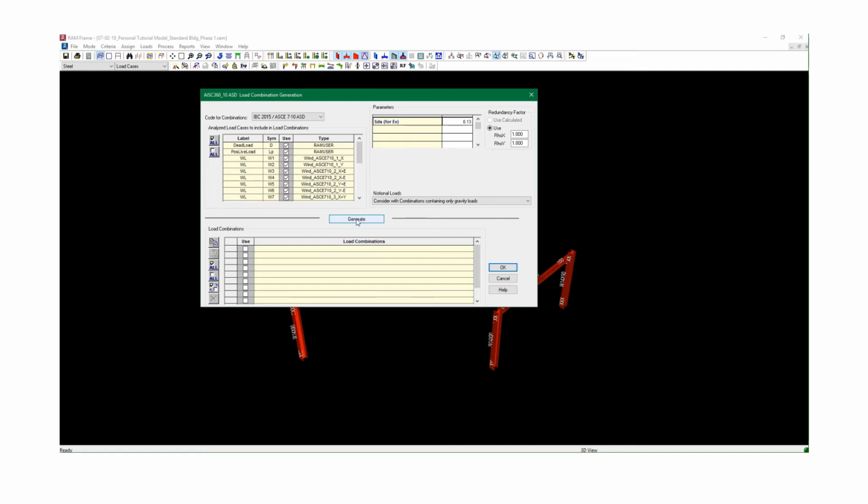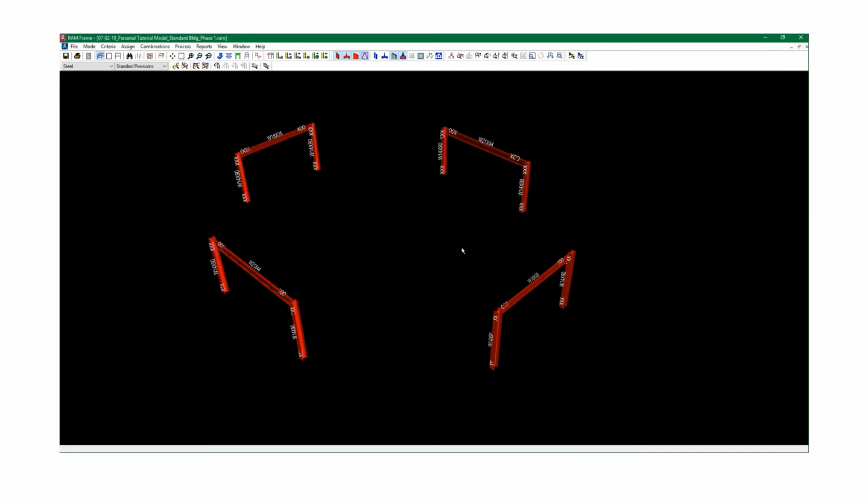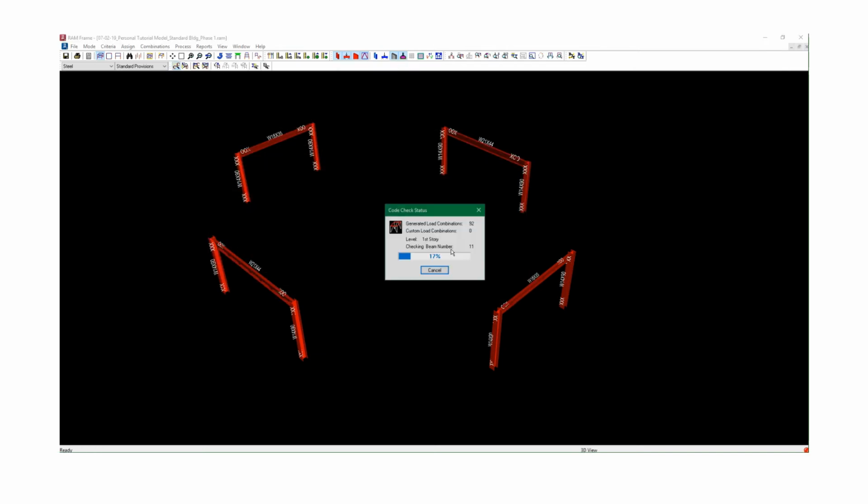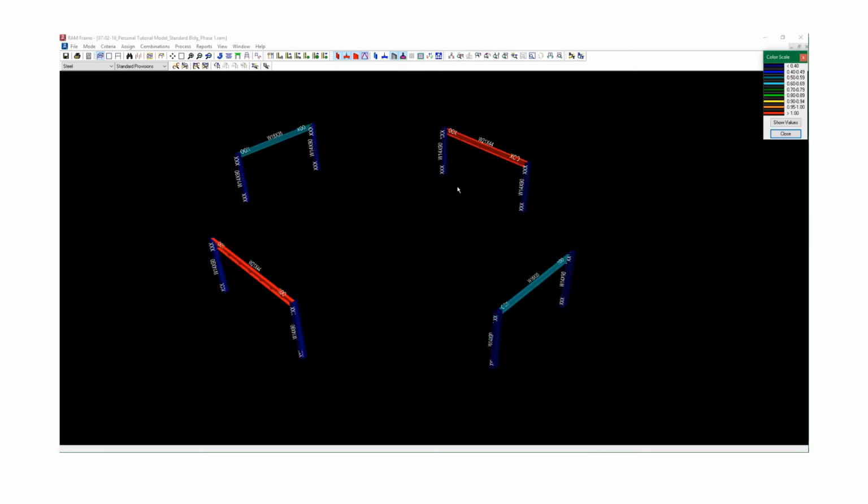So we'll generate the load cases by clicking on that button, and you see from these load cases, we generate load combinations, and that's 1 through a whopping 92 load cases here. Lots of fun. And this is without earthquake and the earthquake eccentricities included. So say okay. And then I'll just run the analysis, and these are your designs.